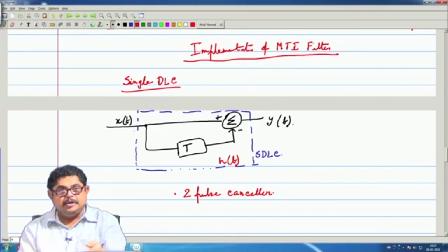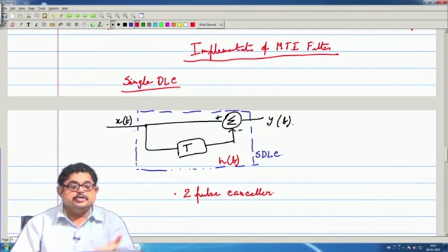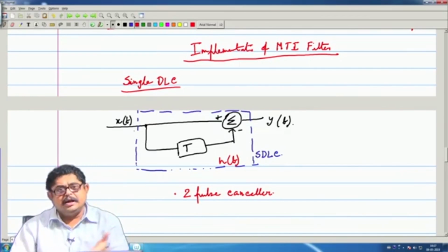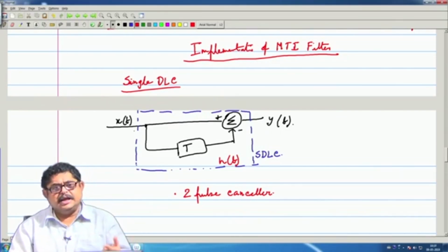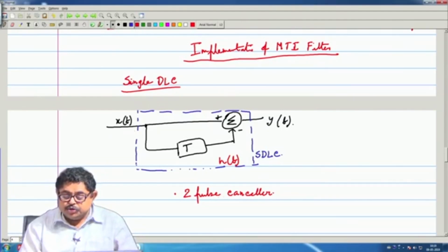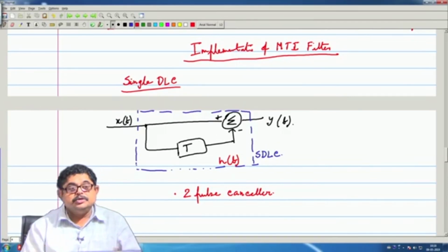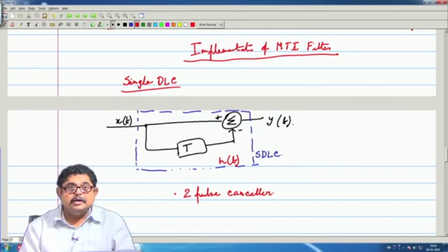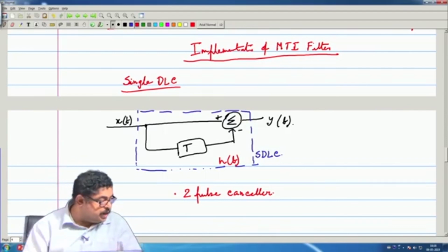you can put in an AD converter, because now these frequencies are after matched filtering and phase detection. So, that is your IF frequencies, where AD conversion is possible. Nowadays, even at RF level you can have AD, at least S band, and I think X band also, but those things are costly. So, this 2 pulse canceller requires 2 pulses: one is the direct pulse that has come, then you require a delay. That means 2 PRIs are required, and only after a time of 2 PRI can you get it.